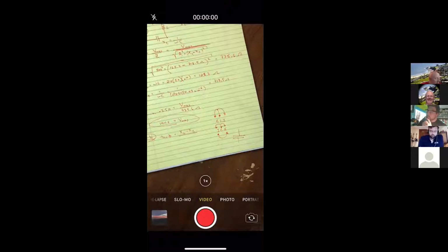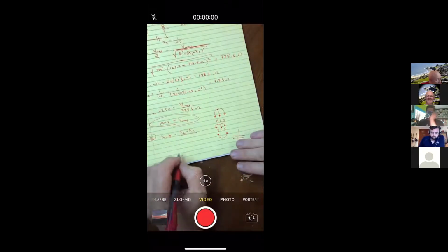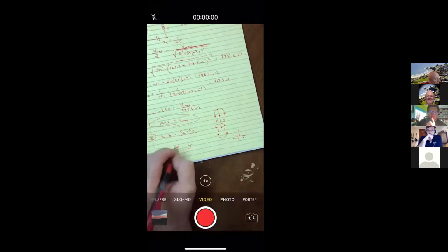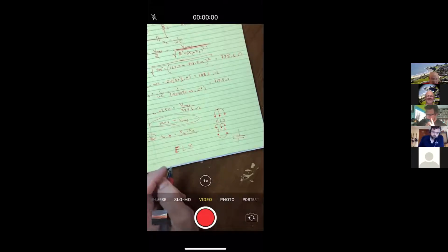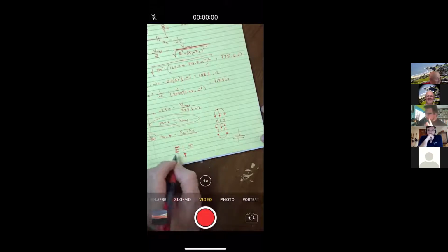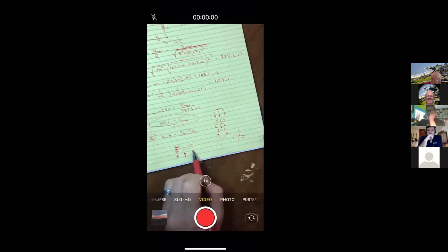Okay, so the ELI, I'll make it a little bigger here. ELI is just a good way to try to remember which comes first in the inductor. Now, I know it's inductor because it has the L in it. And as you see in the word ELI, there is an EMF first, so the E for the EMF, and then the I for the current. So voltage comes before current in the inductor.